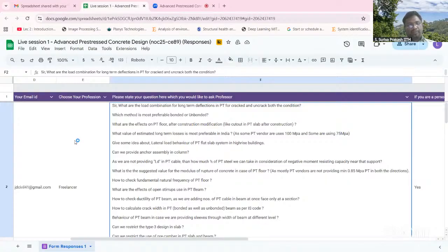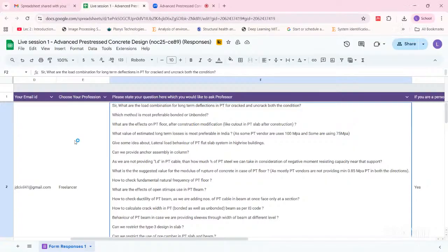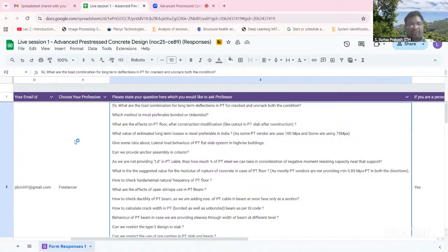Now you see, that's where the construction stage is also very, very important. Because the element was not seeing the dead load, what happened? I have applied compression and you have upward camber, so you have a reverse profile. Because it has not seen the dead load, over a period of time creep was acting in the opposite direction and the camber kept on going up. Do you understand? So that is also important. Too much pre-stress is also negative, so we have to be very careful.